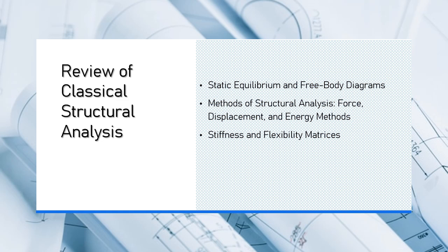3. Virtual work method. The virtual work method is based on the concept that the work done by virtual forces, infinitesimally small forces, in a structure equals the virtual displacement caused by these forces. This method can be used to calculate the displacements in structures with more than 1 degree of freedom, such as frames or trusses. Key features of energy methods.